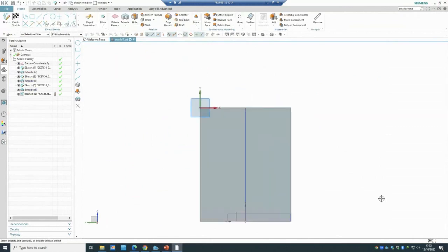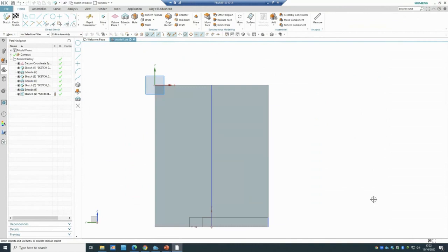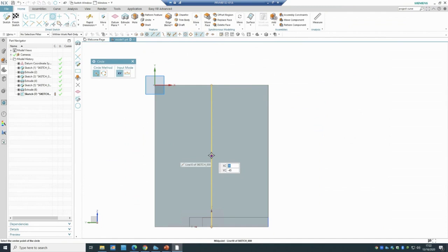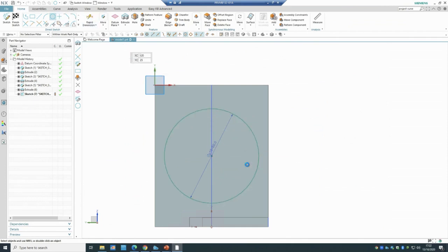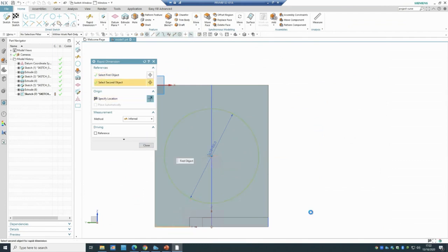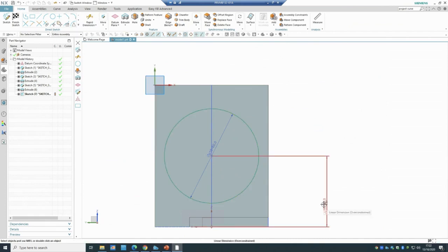So I'm going to start with the main. As I mentioned, there are different ways of doing it, but I think it would be the best one if I go and create a circle in here with, so what I know, the diameter of 60 based on the dimensioning there. And what I know, the center of it up to the bottom of the design has a distance of 48, if it lets me move. Yeah, technically it automatically finds the exact point for me, the exact midpoint.